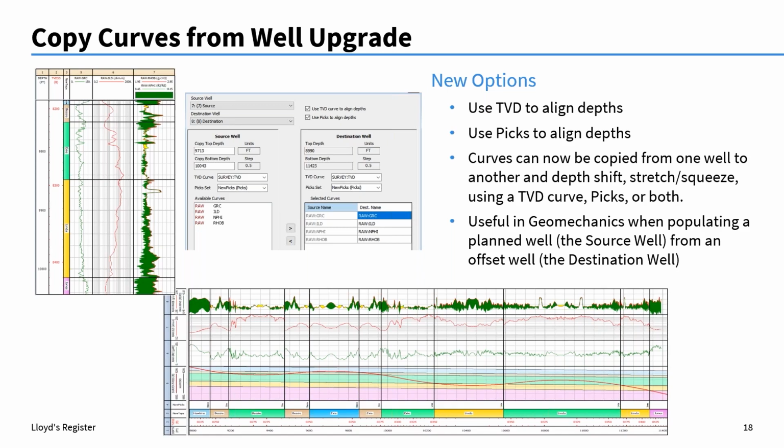And now it will accurately copy them across into the planned well path. So if you're copying in TVD, then it will quite happily work out when you're going back up with overturn sections, repeat sections, things like that. So you get a much better well copy that, in particular, if you want to go ahead and do your wellbore stability planning before actually starting to drill the well.